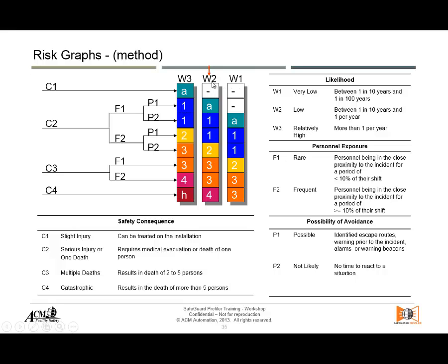The W1, 2, 3, that will be the point of entrance to start analyzing the situation or the scenario, right? So first of all, no safeguards are in there, and I'm looking whether one safeguard, which is called the safety implemented function, how good it has to be in order to reduce risk to a tolerable level. So you can see that indirectly we have a tolerable zone in our risk matrix, and we have to drive from the high risk to the tolerable risk place.